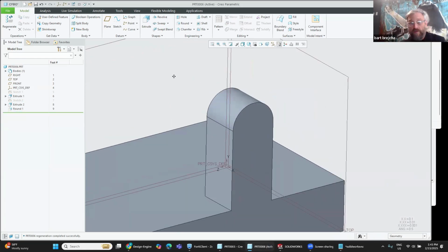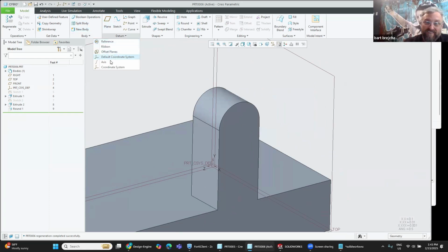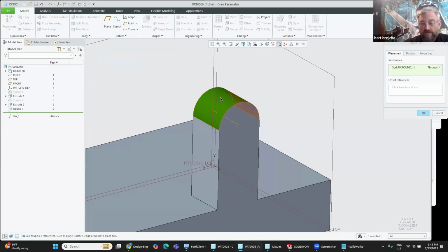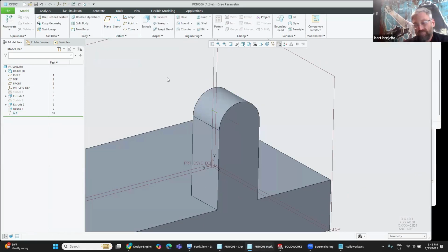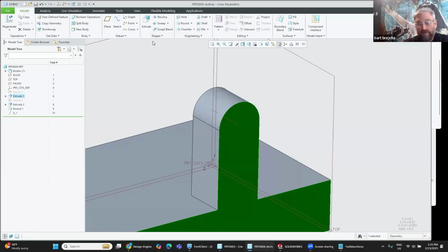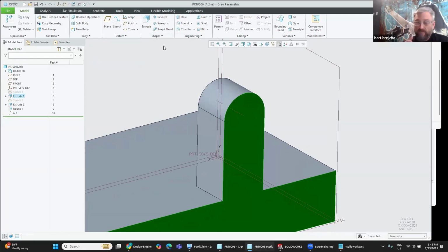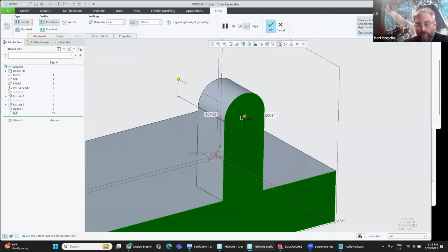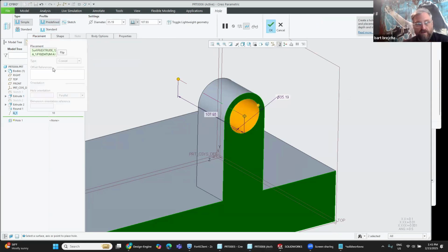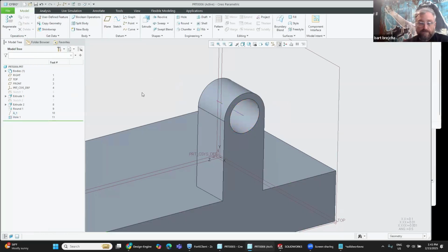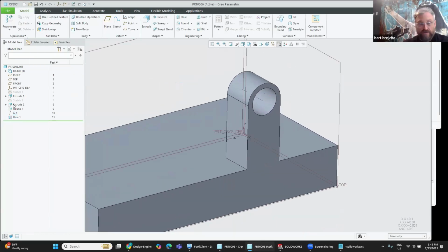Now I'm going to try one more thing. Now this one's got to fail. I'm going to put an axis at the intersection of the cylindrical face. This is something I don't often do: I played the Thomas Edison method. I change one thing and expect a different result. In this case, I'm doing two things, and that's probably a bit of a mistake, but for sake of time, I'm going to put a hole through both of those, and my hole is now fully constrained because inside of it, I'm looking at an axis as well. For some reason, I feel compelled to say through all.